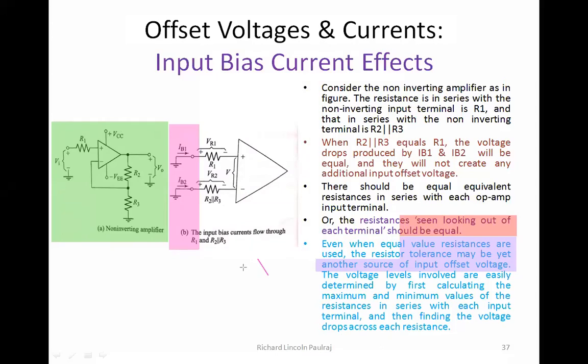Resistance tolerance. You remember? Sir, is it about the maximum voltage a resistor can tolerate? It is like, you will have something at the extreme right hand side, there's a small band, the color coding, you will have plus or minus 5%, plus or minus 10%, gold, silver, all this.